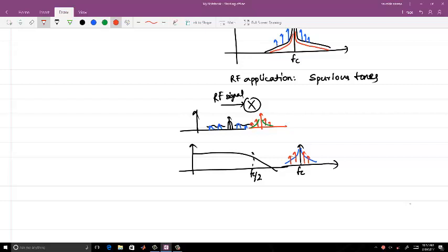In the case of broadband, you look at the total integrated jitter or total jitter on the clock. The spurious tones are not that important, I would say, but just do not make them equal to the main tone. Something like 40 dBc reference per spurious tone is good enough for many broadband applications, but it may not be good enough for a GSM application.